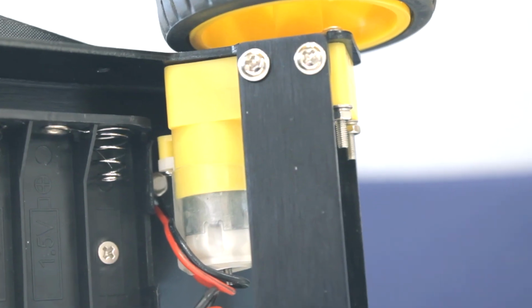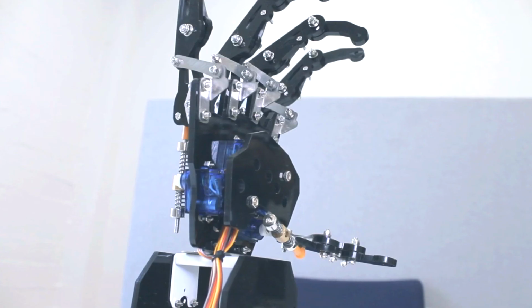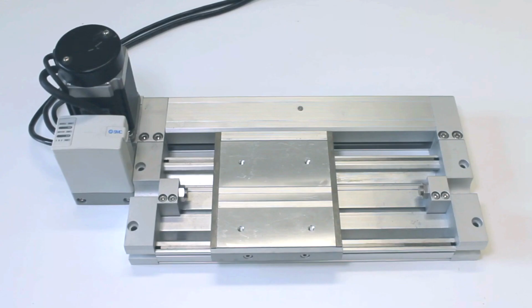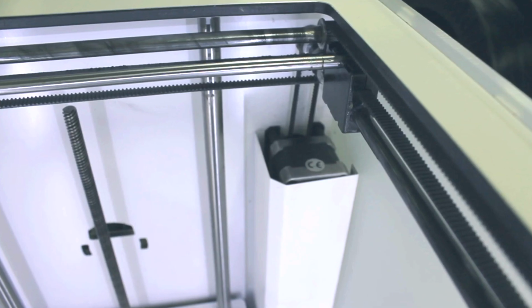Next, some example use cases for the motors. DC motors are used in applications where high rotation speeds are required. For example, radio-controlled car wheels and drone rotors. Servo motors are used when small trajectories are enough. For example, robot arms, claw mechanism, and pushing movements. Stepper motors offer high precision and control. They are used in precise control arm movements, for example, 3D printers.